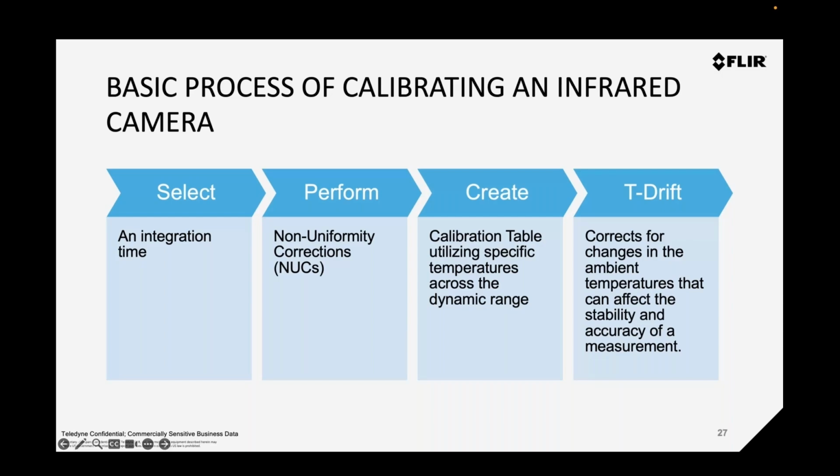And we typically recommend setting the integration time to where the detector fills to roughly 80% at the top end of the temperature range. For a 14-bit detector, that's a little over 13,000 analog to digital counts.